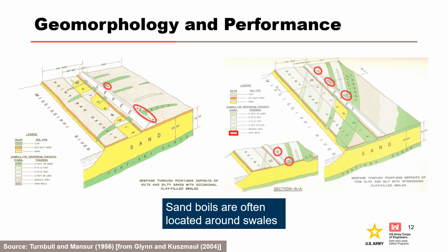In the figure on the left, ridge and swale topography in point bar deposits concentrates seepage and results in more observed sand boils. It is important to understand that three-dimensional concentration of seepage, once a defect has formed, will also make progression to breach more likely.